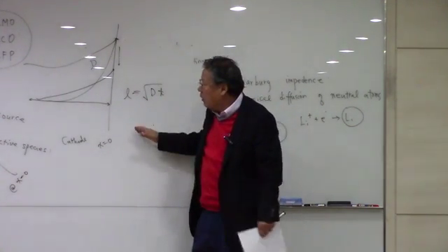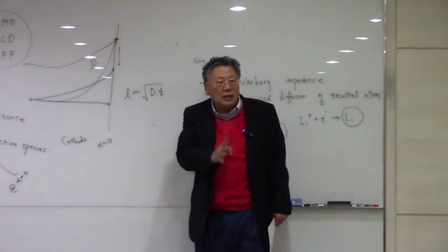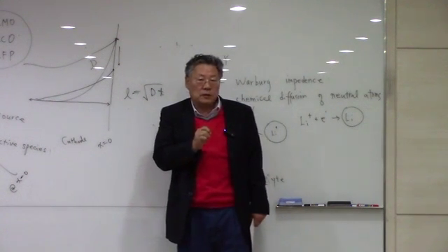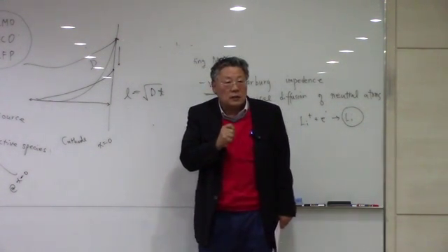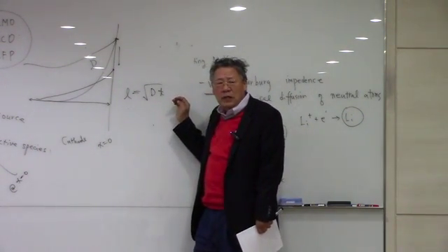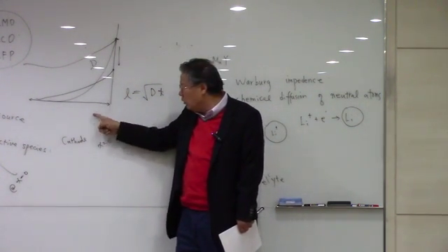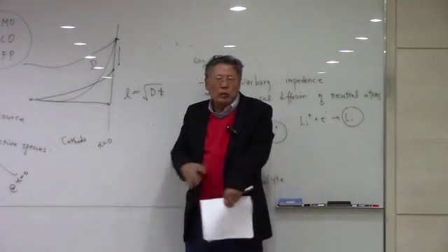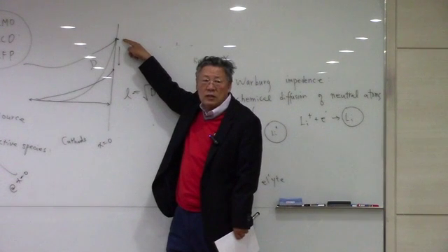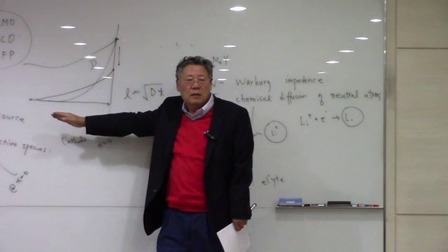So for cathode materials, you have to have a high diffusion coefficient of electroactive species. Can you see this? Otherwise, only a little bit of lithium or electroactive species is going to be inserted in your cathode. It is going to ruin all the voltages, because the surface concentration is not going to be diluted inside your material.